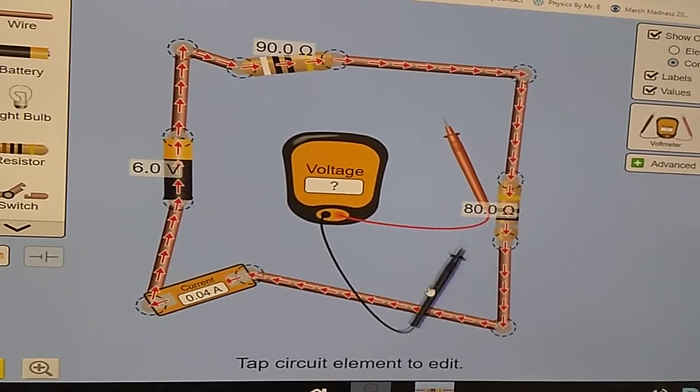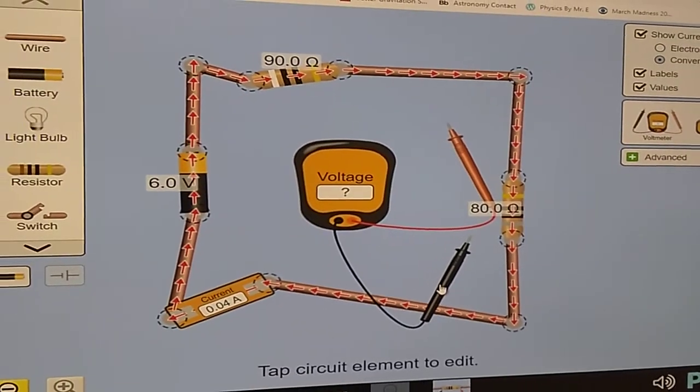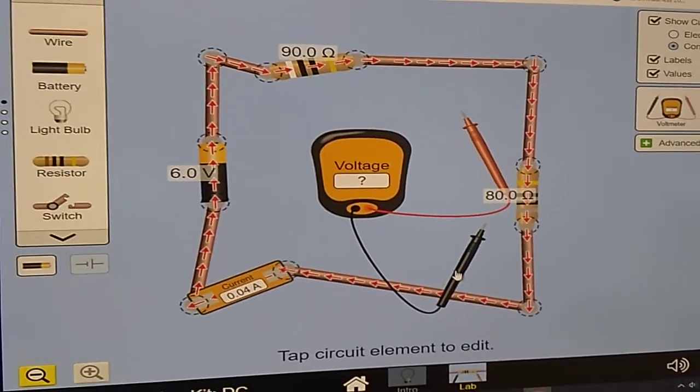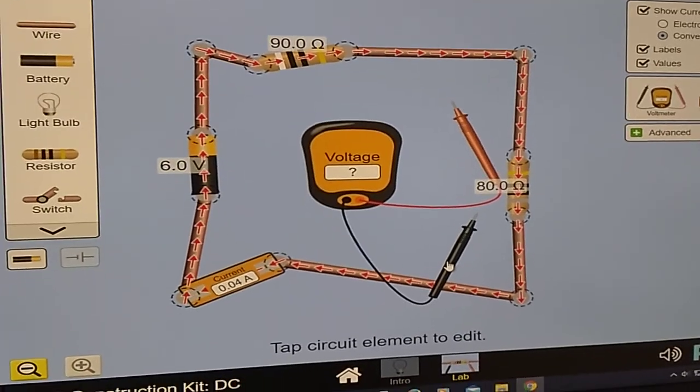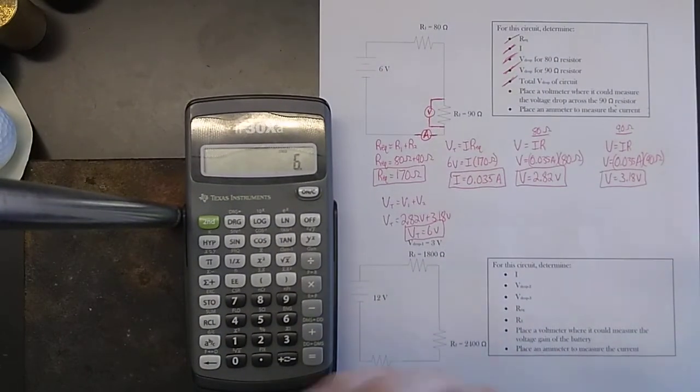They've just reversed. So the voltage drop doesn't go with the order of the resistors, it goes with the size of the resistor. Okay? Notice also that the bigger resistance has a bigger voltage drop. And that makes sense if you think about it in the context of Ohm's law. Okay? So that's a very basic series circuit problem that you might see.